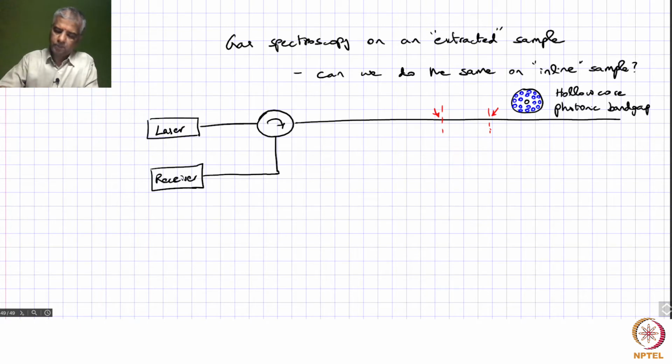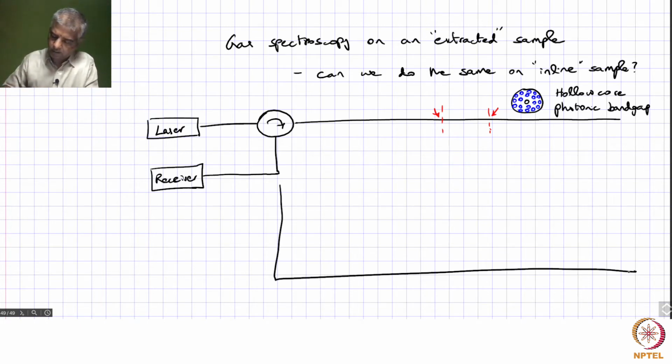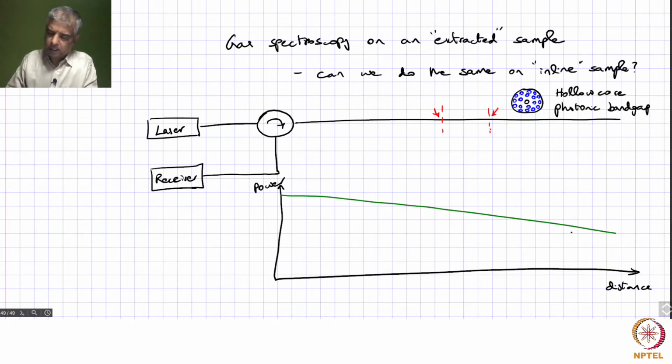So what we are talking about is, if we look at the backscattered light power as a function of distance, right. If you send light at some background wavelength, then you would just have this linear line, especially if you are expressing power on a log scale.